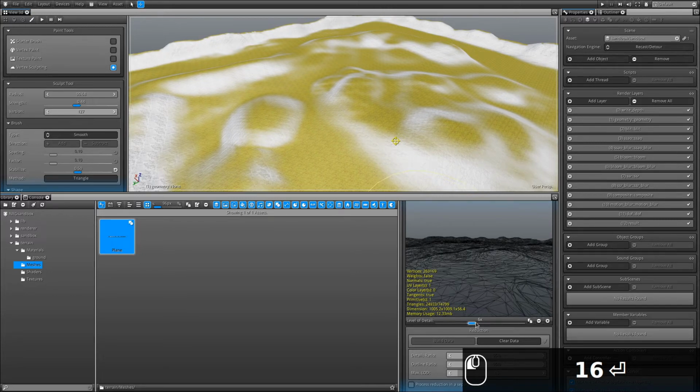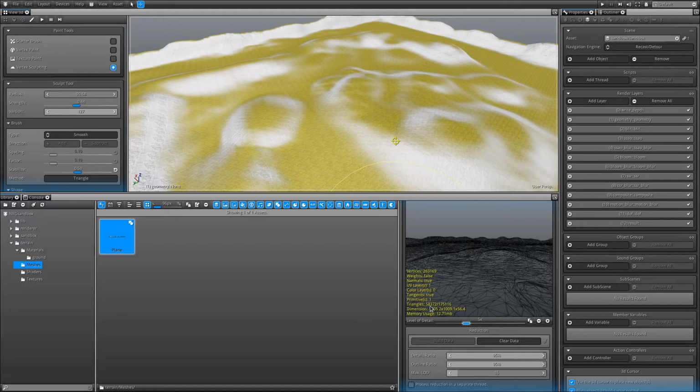I think something in this range of 25,000 should give good results, or we can go slightly higher, 58,000, which is about 10% of our original geometry here.